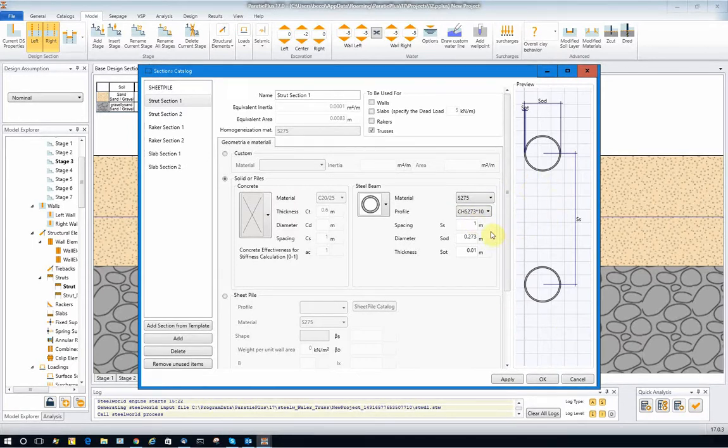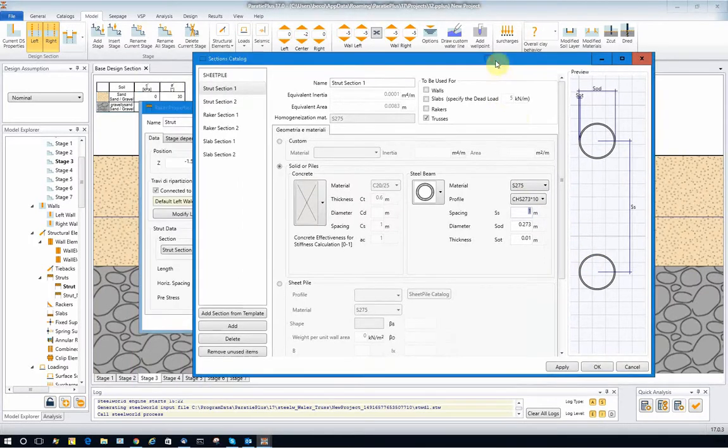Of course, when we define the spacing of the strut, we must here put 1 as the spacing for the cross section. So in this case, what we did is simply say that at 5 meters there is a pipe with this diameter and this thickness, and with this property and this material, of course, steel.